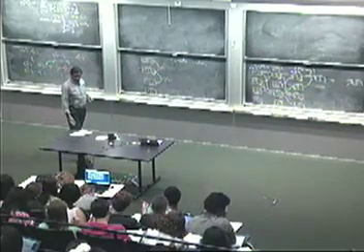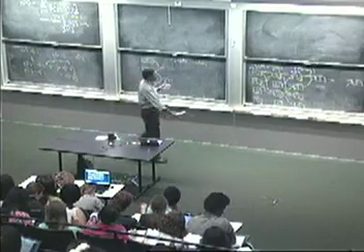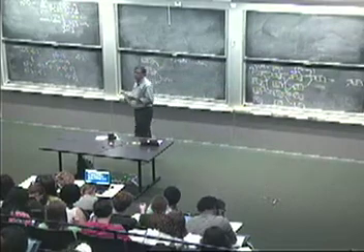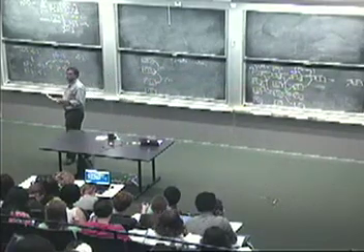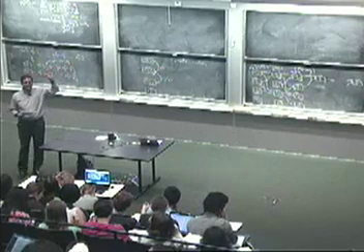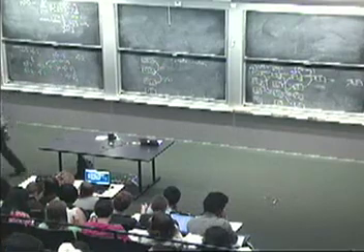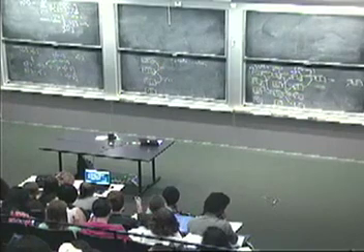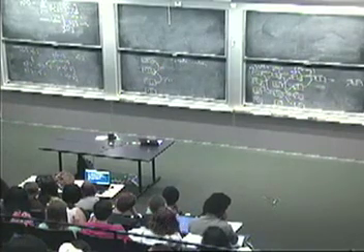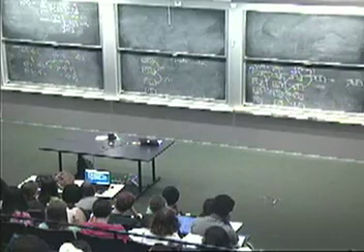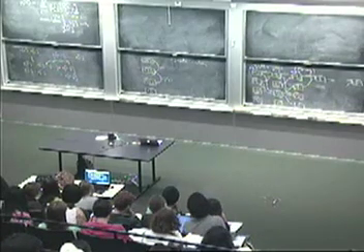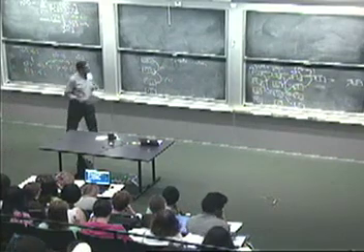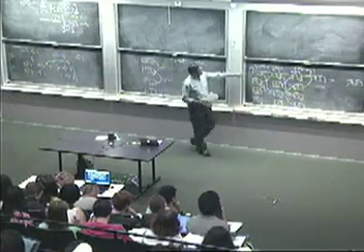How would you look for a minimum Hamming distance in the set of code words generated over this window? The minimum number of ones in a non-zero code word, right? Okay, so it'd be the minimum weight code word you'd find among all the non-zero code words. So you would have to find a path starting here.